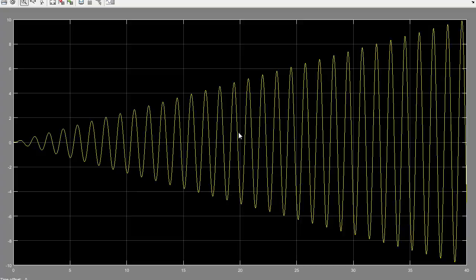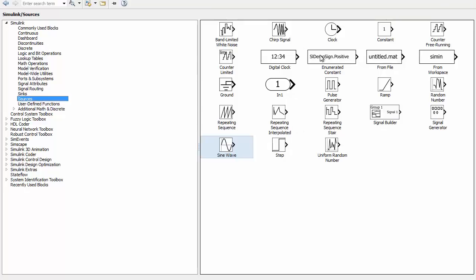Like these examples that I explained to you, you can try other scenarios. For example, one can assign a value to the damping coefficient of the system, and put the excitation frequency equal to the natural frequency of the undamped system, and then see what will happen to the response of the system. Actually, there is so much more that I would love to share with you about the operators here in the Simulink environment and also other libraries. But hopefully this basic review of Simulink covered enough to get you started and explore on your own.